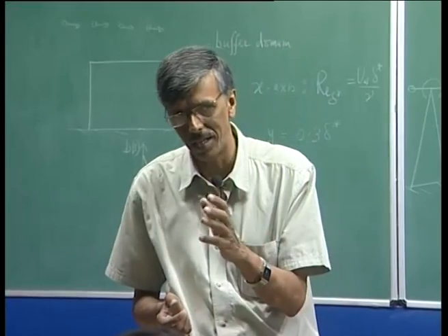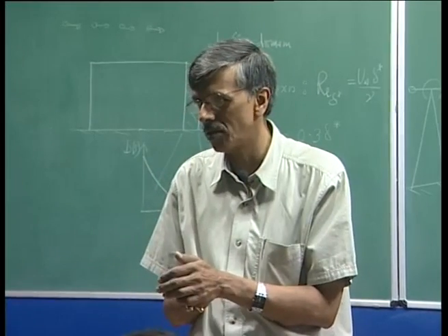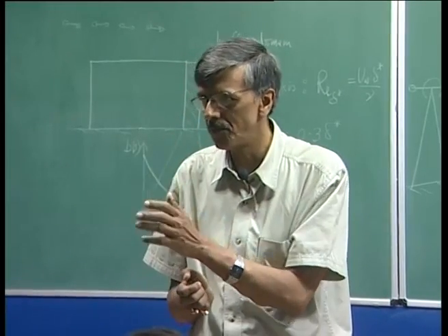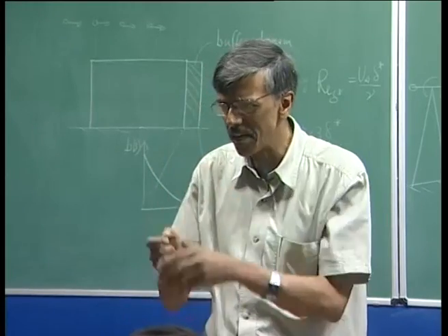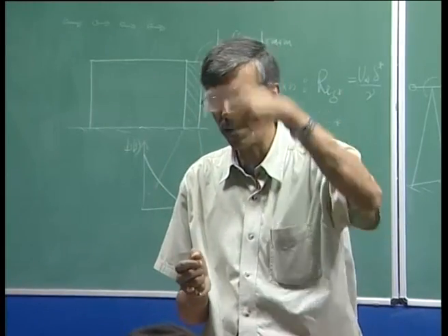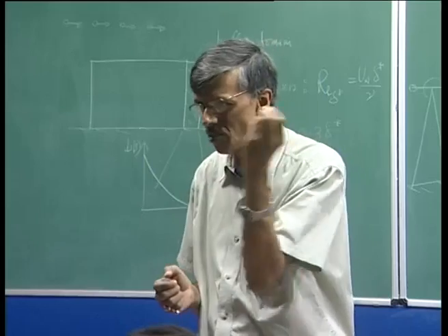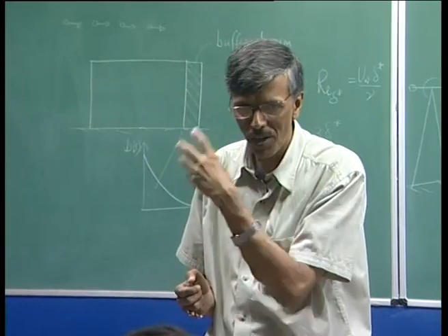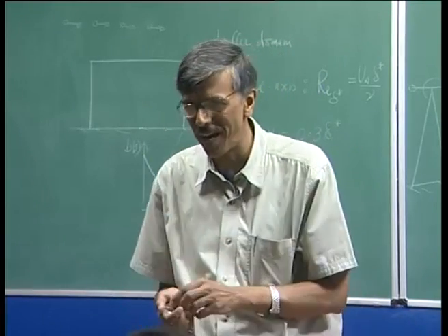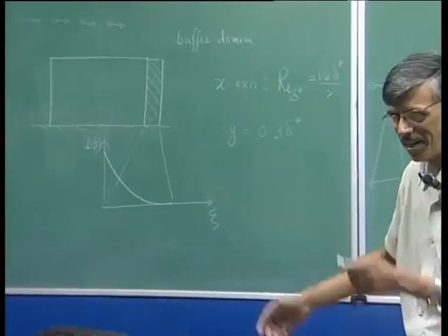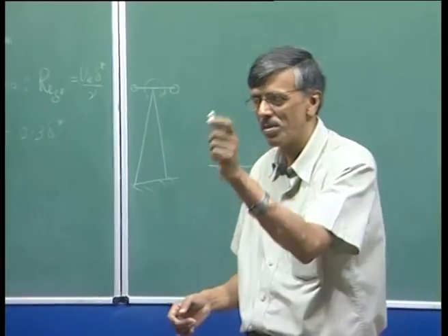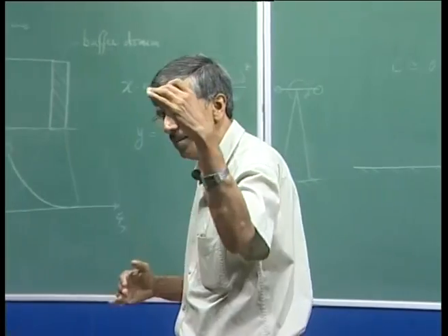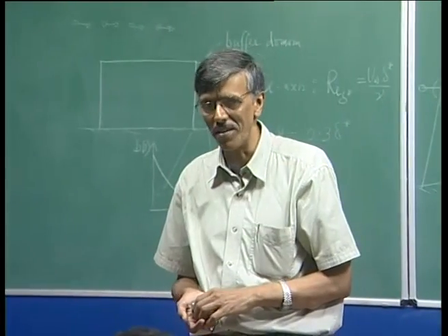But if you look at the compressor part, and at the stator behind a rotor, the rotor is rotating, so it is going to give out periodic vortices, exactly the same kind of thing. So, instead of a flat plate, you should be talking about a compressor blade and vortices going there.